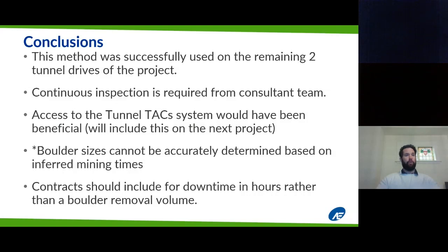I think it's important to note that boulder sizes cannot accurately be determined based on inferred mining times, but in this case, it was an agreed fair and equitable way of compensating the contractor. And going forward, contracts should include for downtime and hours rather than boulder removal volume as it pertains to pressurized phase tunneling. So as we move on, we are going to take a look at putting in hours and time rather than boulder volumes.